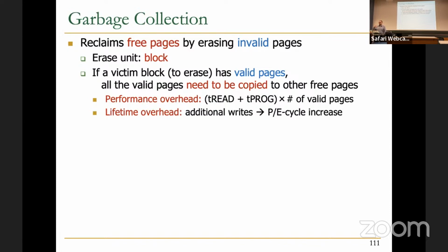Now you have some write amplification. The larger the write amplification, the more your SSD is doing aging-related work because of program erase, and also performance issues. So you always want to keep write amplification as low as possible.